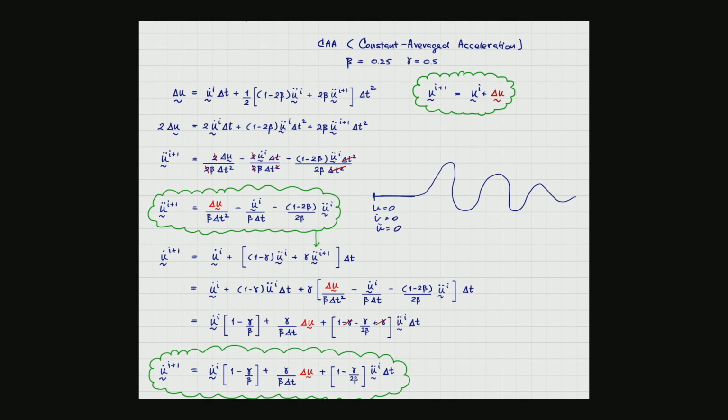The initial condition you give over here is not going to give a very sudden, hard time for the convergence, or a hard time for the solution calculation in the equilibrium. So everything starts from 0, and then you just ramp up your excitations, and you're going to get nice simulations from the dynamics point of view.